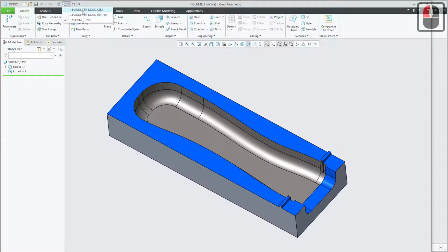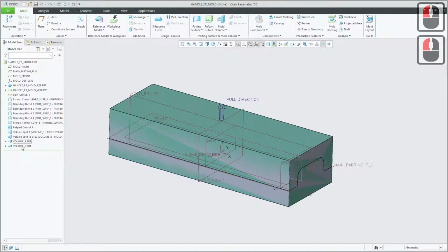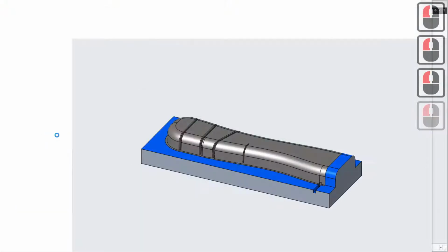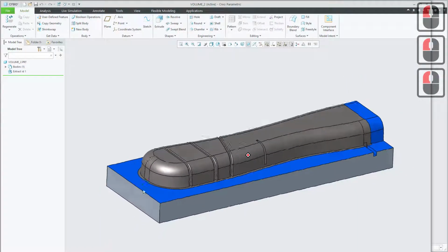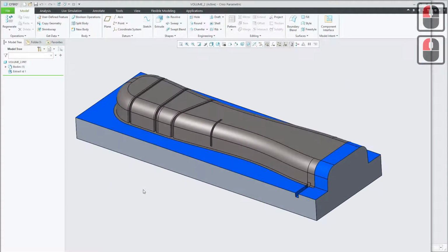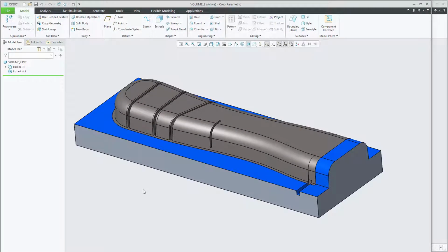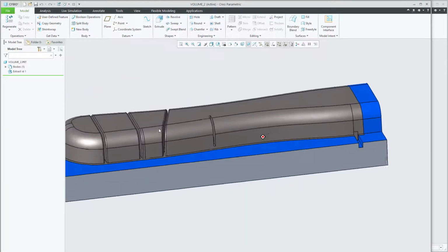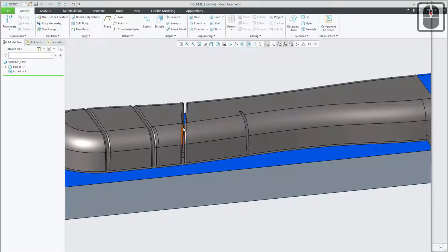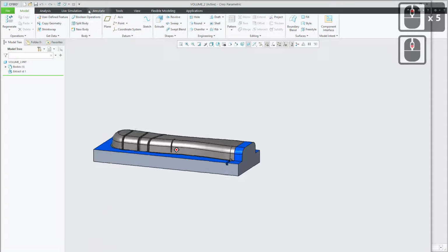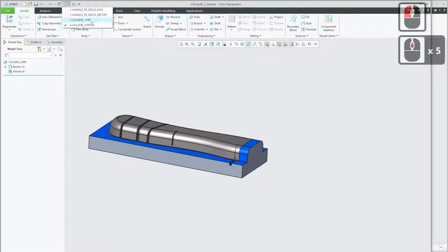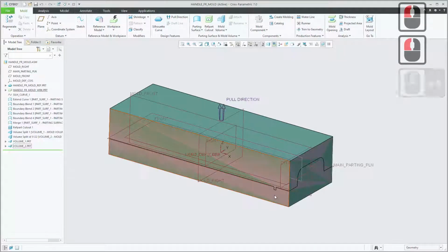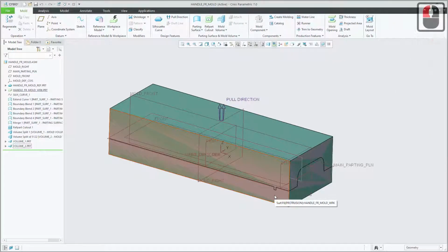And then if we go back to the mold assembly here, we've got the other half of the mold at the bottom, so I can open that up. This half of the mold is responsible for molding all the surfaces on the inside of our handle design. So you can see the negative shape of the ribs here specifically. So we ran through all those steps. We created these two halves of our mold, and now what we're going to look at is some of the more advanced features that you can add to a mold.